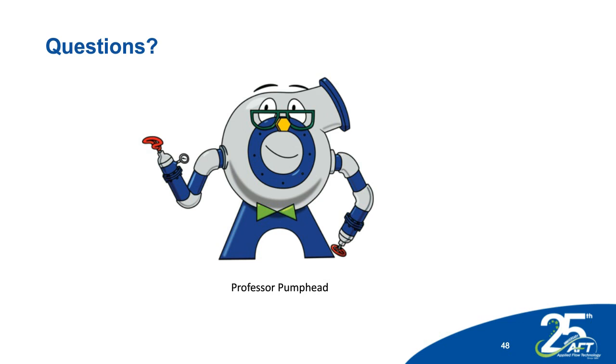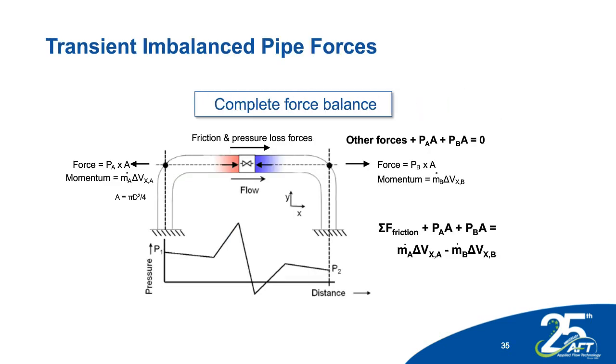Okay, good. And here's an interesting question. How are pressure surges used to assist design of external pipe supports, assuming that maximum surges are kept below the minimum pipe wall stress levels? Yeah, that was something that I alluded to in the slide that I'm showing right now, that what comes out of any Waterhammer simulation, if an Impulse does this, it captures the transient pressure differences and the forces that occur between parts of the system, and that would affect your pipe supports.